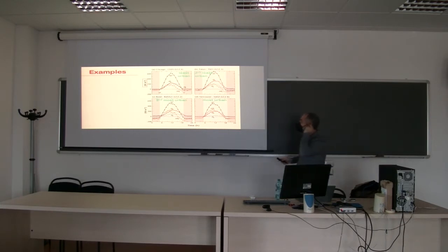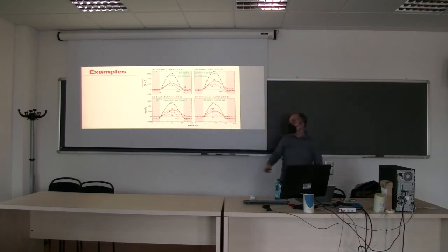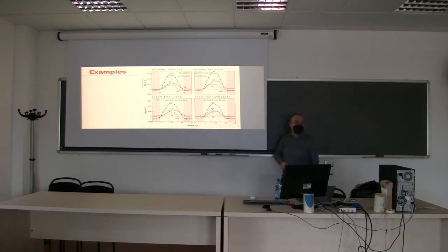So you notice again that when you go from soils to concrete, we're going to talk about concrete, it's a very good storer of energy. This heat storage increases, and that heat storage is stored during the day and released during the night. So it's like a thermal battery, right? And this release of heat is going to contribute to the nighttime urban heat island.